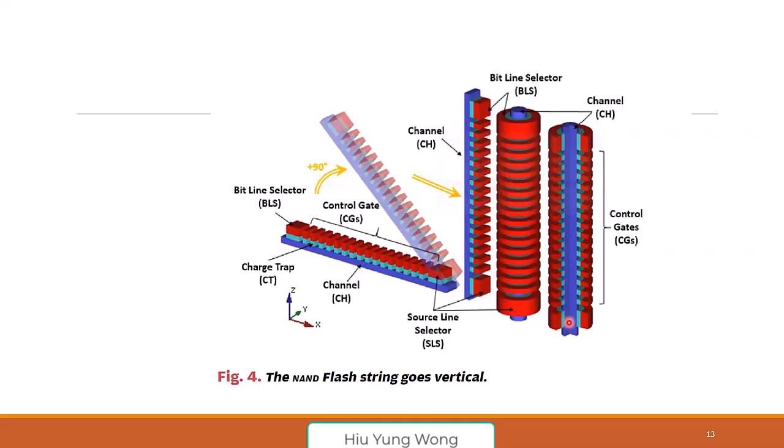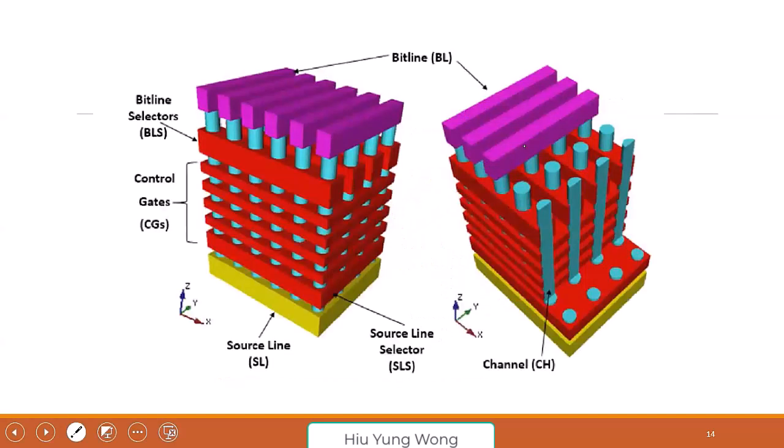But nowadays, because of 3D NAND, you actually need to buy a lot of deposition tools, because you deposit 128 layers, and including the isolation, it means 256 layers. That takes a very long time, so they need to buy many deposition tools. And also etching: once you deposit, they etch a really, really high aspect ratio hole. So this is again important. Then they fill it up with the oxide and the channel, and you get this array of strings. Then you pattern on the top, and so now you have the 3D NAND.